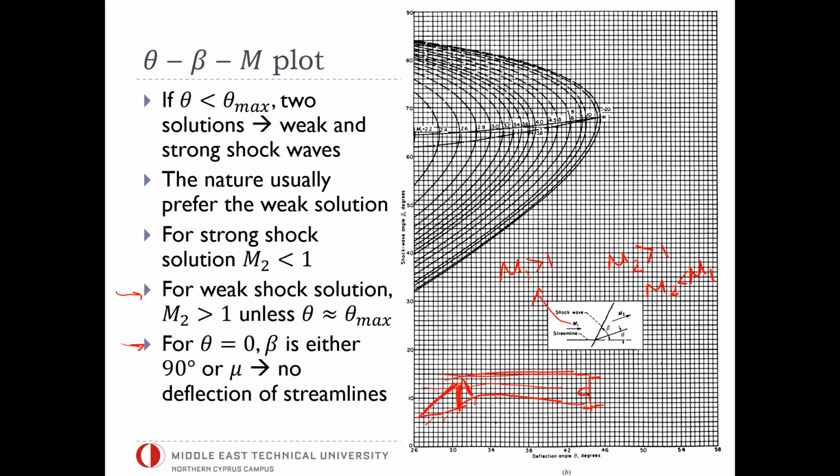Now the thing is, regarding the performance of the engine inside, you would like to have as high stagnation pressure as possible. So the stagnation pressure is already high outside because of high Mach numbers. You don't want to lose a lot of it because of this deceleration when you reach the face of the engine. So that's one important reason.